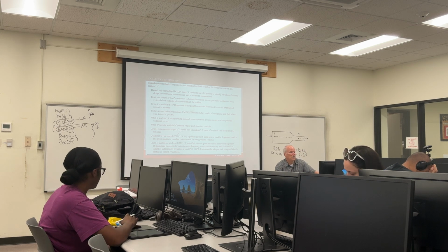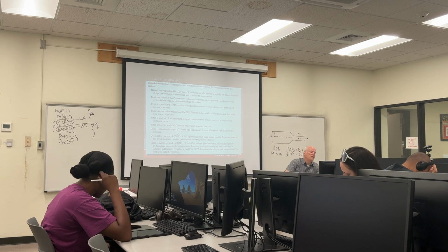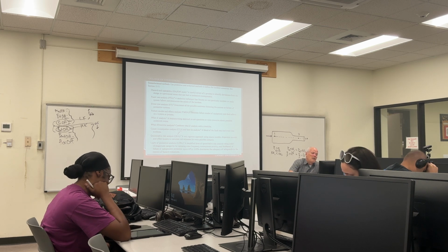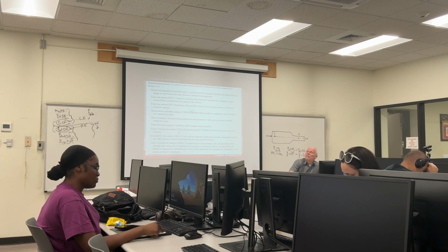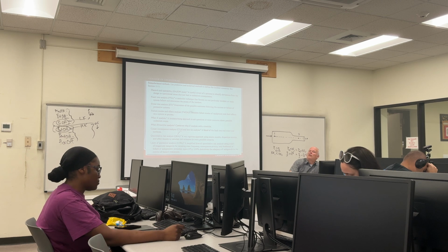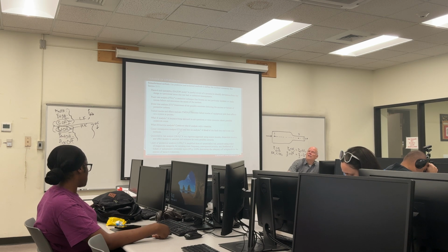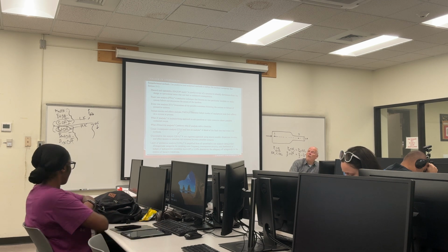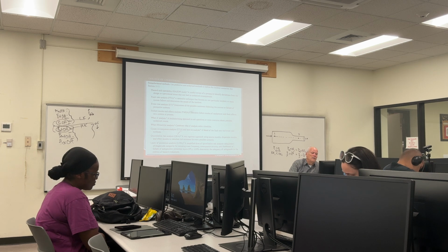And then you got the layer protection analysis, which is a quantitative risk analysis, but we do it based on an order of magnitude. And we have some limiting assumptions that make it plausible that we can actually do a LOPA, but we cannot do a QRA. So you can do a LOPA and it gives you the order of magnitude risks that are associated with some hazards.